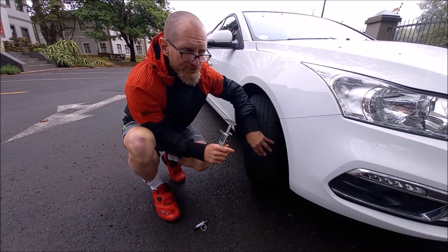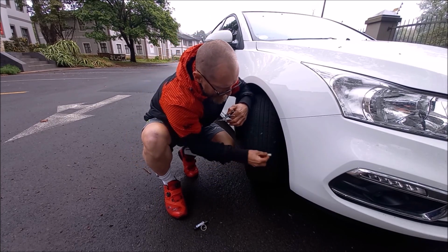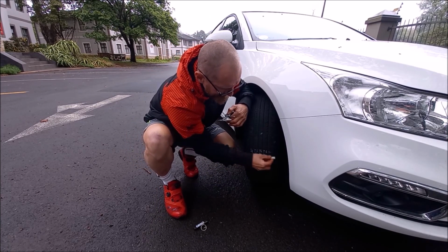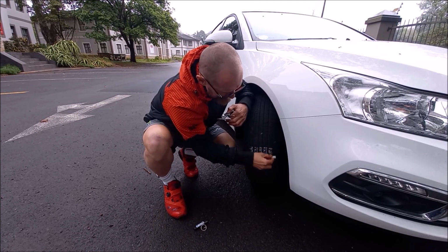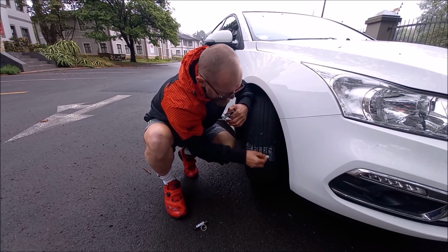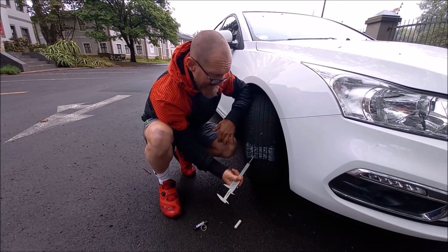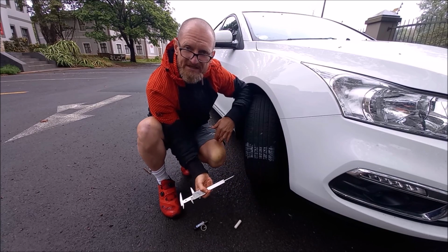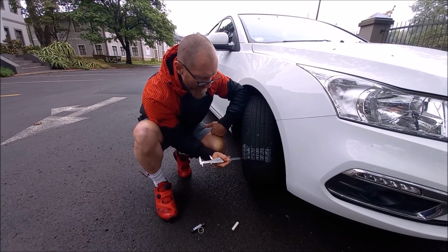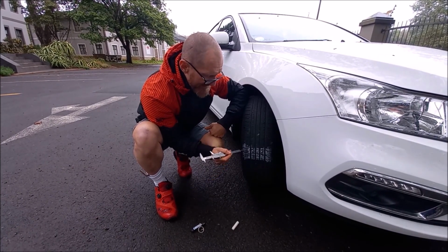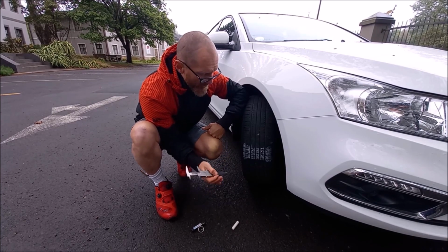Right. So what we would do when we measure the tire, the very first thing we would do is take chalk and make a little bit of a surface across the tire. The reason we do that is because when we're taking photographs, it makes the channels stand out nice and proud in the photographs. That's the only reason we do that. You can see it very clearly. These little lines on the side here are referred to as sipes. Even in the National Road Traffic Act, you have to be able to see those sipes. They may not be worn away to the point where you cannot see them anymore.